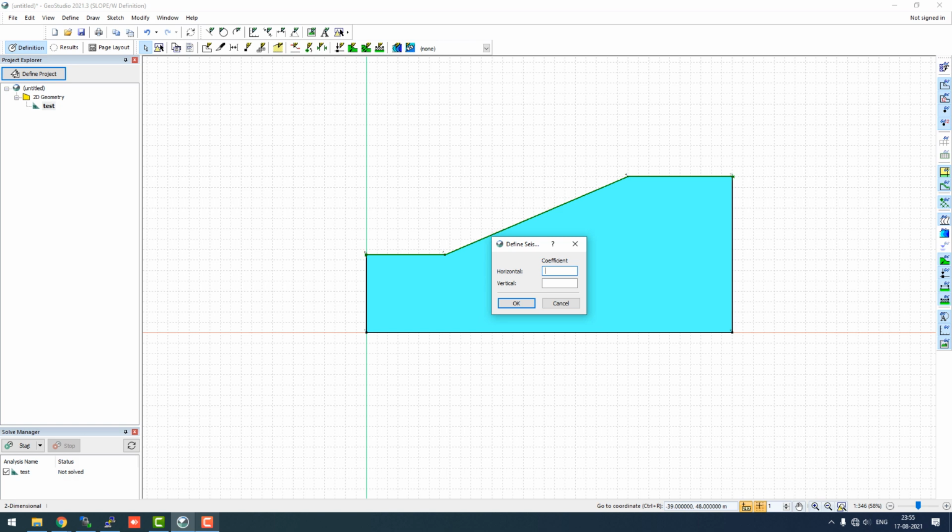However, you can take dummy values of 0.15 for the horizontal seismic coefficient, and 0.1 for vertical. That will be good enough for your understanding right now. But you can check out Indian Standard 1893 or other parts where you can calculate these values based on the zonal provisions provided in Indian standards.